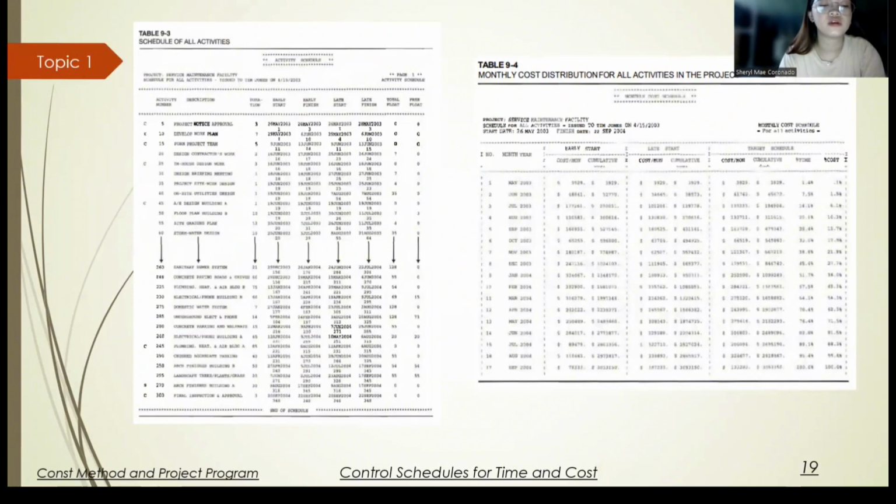Critical activities are those activities that have zero float time and are denoted by the letter C. At the left of the activity number, major milestone events are also noted on the schedule. This schedule is a summary level scheduled report that integrates engineering, procurement, and construction.